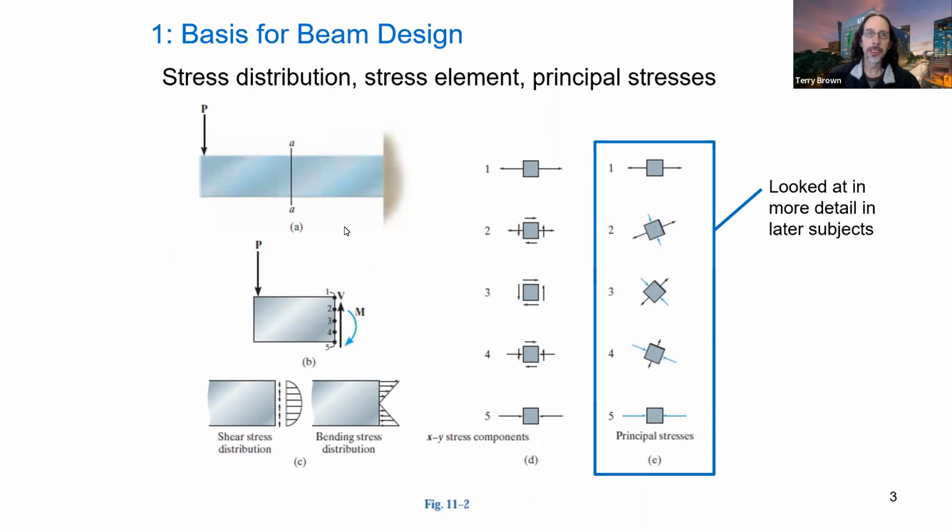In the last few weeks, I've asked you in doing the tutorial problems to sketch the stress distribution. It's good to know how the stresses vary throughout the beam, especially if you're going on to do finite element analysis and structural simulation using the finite element method, to be able to look at a solution and say, no, that doesn't look right, there's something wrong there. And that ability comes from knowing how the stresses should vary through the cross section.